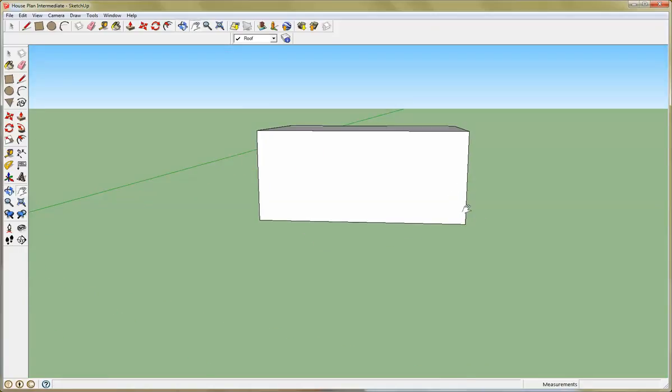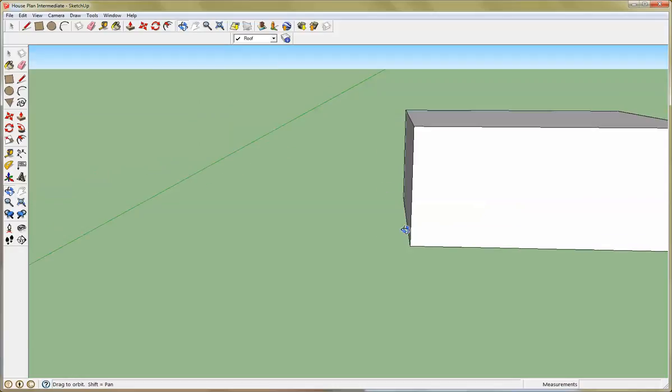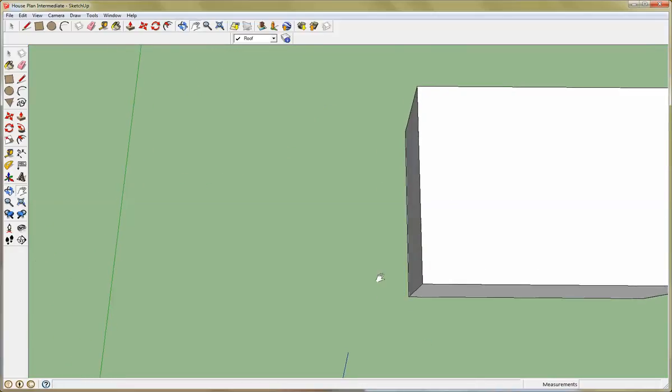I like to sometimes make tools, and we're going to make a 12.5 slope tool. Pretty simple. Starts by, get a downward view, make another rectangle. Make the rectangle 12 inches by 12 inches. So 12, comma, 12. Notice I did not put the inches symbol on our dimensions. Google SketchUp or SketchUp will automatically assume you mean inches if you leave the symbols off.